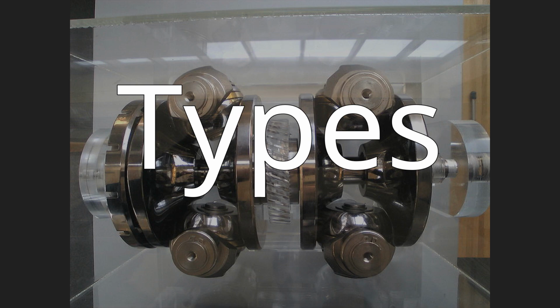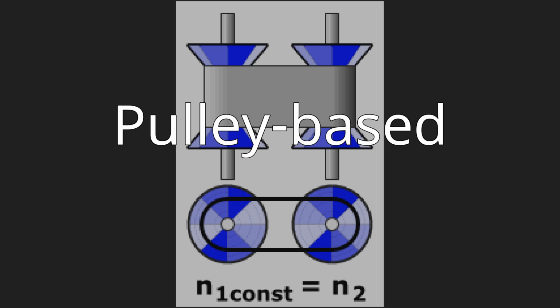Types: pulley-based. The most common type of CVT uses a V-belt which runs between two variable diameter pulleys. The pulleys consist of two cone-shaped halves that move together and apart. The V-belt runs between these two halves, so the effective diameter of the pulley is dependent on the distance between the two halves of the pulley. The V-shaped cross-section of the belt causes it to ride higher on one pulley and lower on the other.